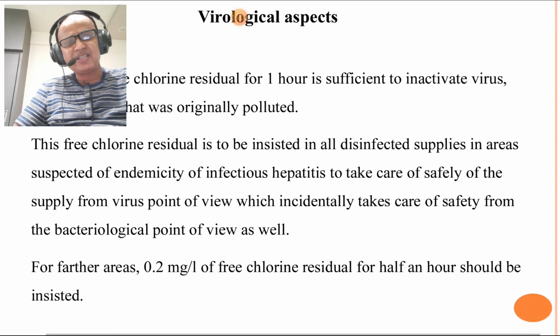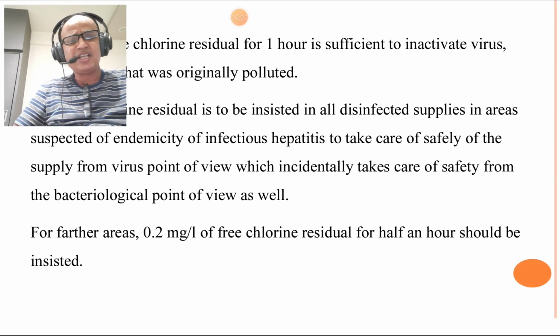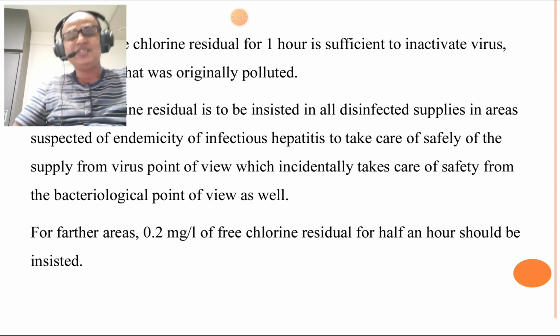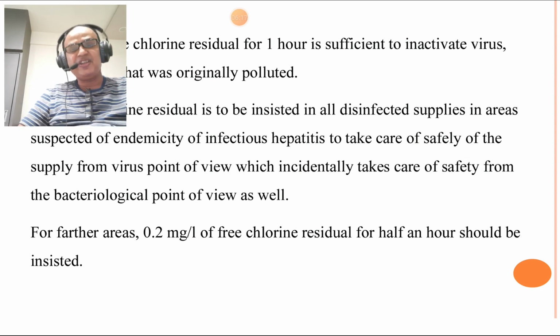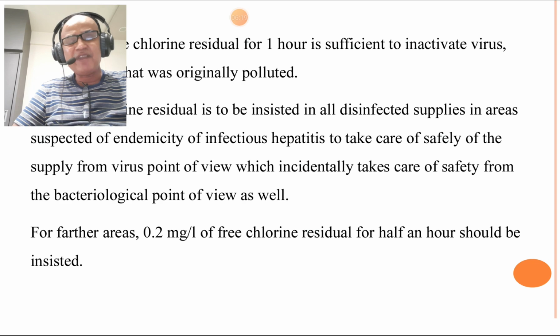For other areas, 0.2 mg per liter of free chlorine residual for half an hour should be insisted on. So free chlorine is very much essential to avoid virus infections through water, and a 0.5 mg per liter dose for 1 hour is sufficient.